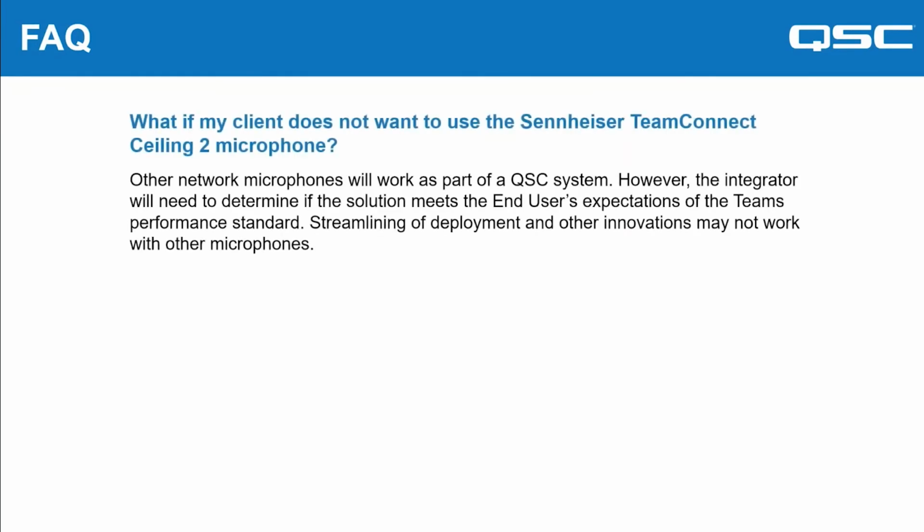Now, I've just got a couple of frequently asked questions I wanted to touch on before we wrap up. Firstly, what if I don't want to use a Sennheiser microphone? What if I'm standardized on some other microphone? Well, as we all know, technically that's fine. Technically, other network mics are going to work with Qsys, but it all comes down to that Teams Room certification element. So if the end user says, well, all these spaces, of course, they need to be Microsoft certified, and you have different microphones with Qsys, it's not going to meet that element we talked about earlier, where the complete audio signal path needs to be certified. And that might not matter to the end user, or it might be really important. So it's just a discussion you'll need to have.